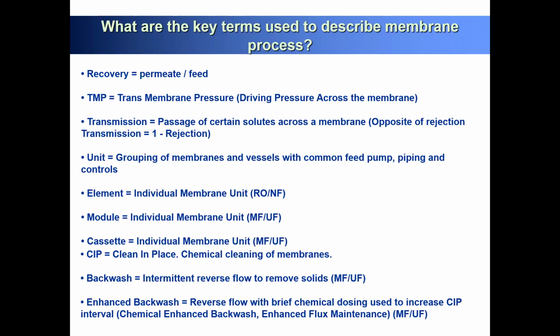Unit: the grouping of membrane, vessel, and pump piping. So when you design your assignment, okay, we would like to design 250 million liters per day. So we don't design 250 million liters per day all together. We just separate one unit. One unit, I want to design 10 million liters per day, or 1 million liters per day. So when you design your assignment, don't design all capacity of 250 million liters per day. So you just